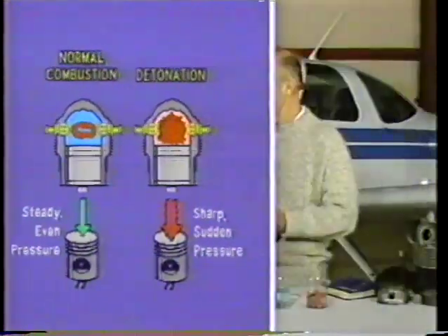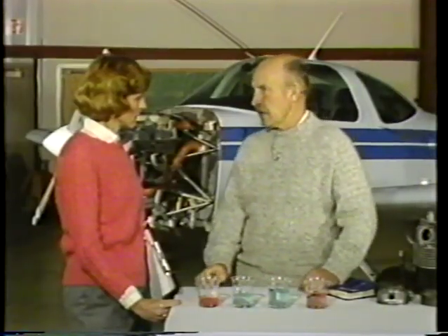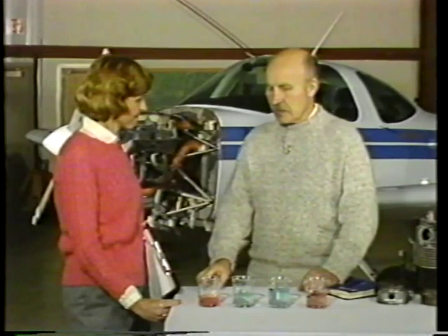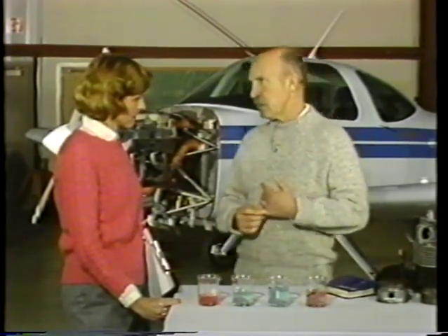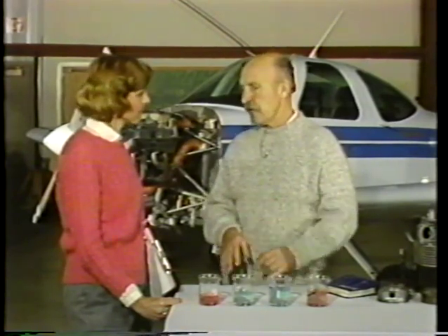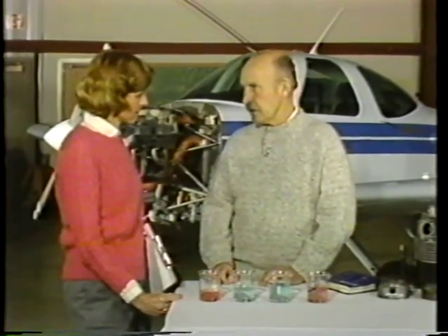In fact, in automotive engines, when you hear it ping, that's detonation. And so detonation can be caused by that. Detonation can also occur if we use automotive gas in the airplane. We should never mix automotive gas in your airplane.